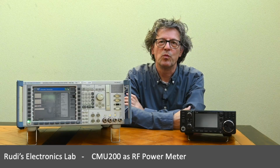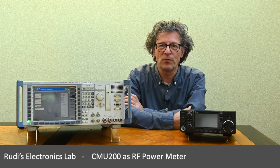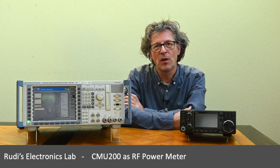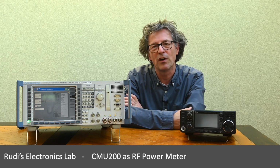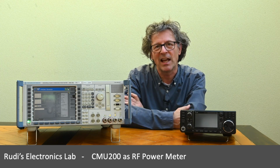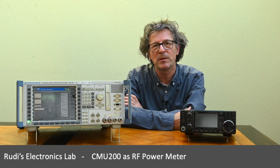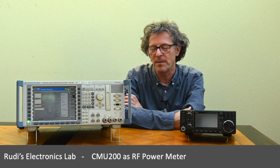So, what can we conclude about the CMU as a power meter? I think it's got a couple of quite interesting features. It can handle all the way up to 50 watts directly into the device. That is rather unique. Also the fact that it's part of a general purpose instrument that you might actually purchase for its other functionality makes it really attractive. And it has a true wideband power meter, diode based, in addition to the functionalities I also discussed in the video, like the frequency specific power meters with specific filter settings, as well as measurement of power versus time.